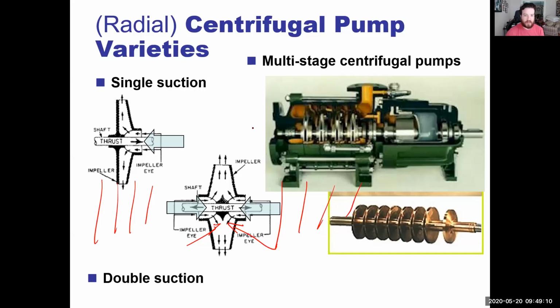I mean, you could, but the only problem is that it's not like you're going to get more flow out of it. Really what you want with these things, and that would kind of be running in parallel, which you're not allowed to do with centrifugal pumps. It's not good for it. They can run in series. You put one after each other, and that's why these multi-stage work.